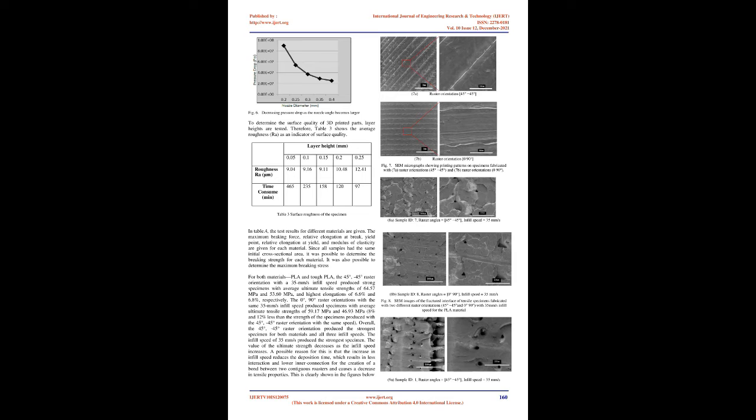3. Results and discussion. As the nozzle diameter varies from 0.2 mm to 0.25 mm, 0.3 mm to 0.35 mm, and 0.4 mm, the pressure drop can be seen in Figure 6. The pressure drop increases as the outlet nozzle diameter narrows. In comparison to the 0.4 mm nozzle diameter, the 0.2 mm nozzle produces a pressure drop that is almost 3 times greater. There is a strong relationship between nozzle diameter and pressure drop.